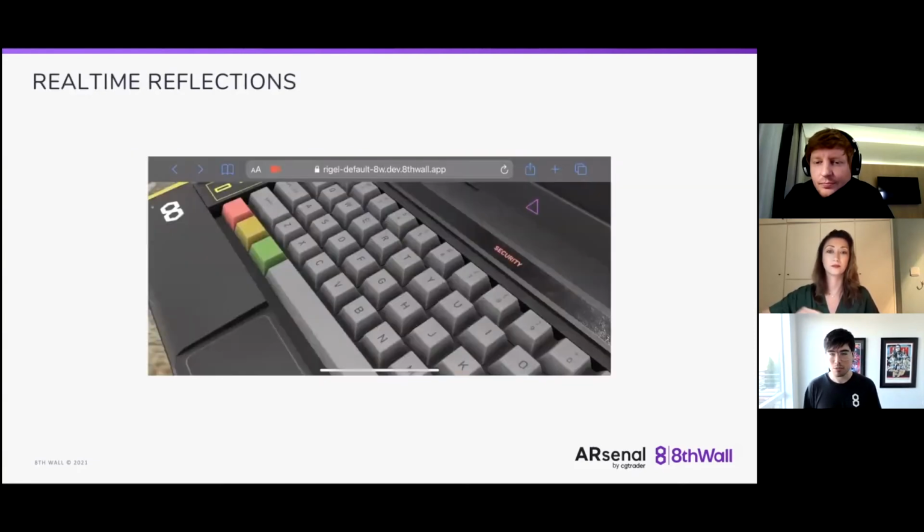if you have a stray 8K texture that's really bogging down your scene. We're also displaying active image targets that are coming in and out as you cycle through them, what your load time is, so you can work on reducing that, and even your estimated app size. So taking all of the objects in your scene and adding them up to see if there's anything in particular that's really bogging it down when it loads. We also have a real-time console that's streaming in all your console logs. And so anyway, look forward to that. I'm really excited to see how that'll help with this exact topic.